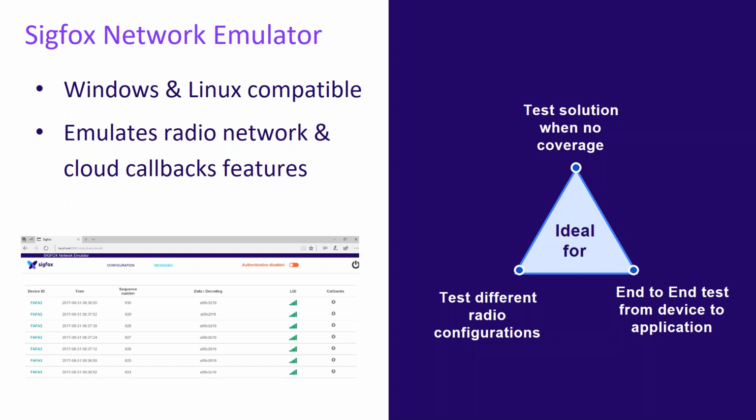The other use case is, as you may know, that with Sigfox we have different frequency bands. We've got a radio configuration 1 in Europe, which is using 868 megahertz. But if you go, for instance, to the United States or Mexico, it's a different frequency, which is 902 megahertz. If you go to Latin America or to Asia, it's going to be 920 megahertz. So you've got different radio configurations. And using the SDR dongle, what is interesting is that you can choose from the different radio configurations and test your IoT solution for different regions.